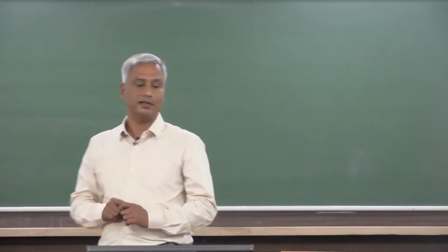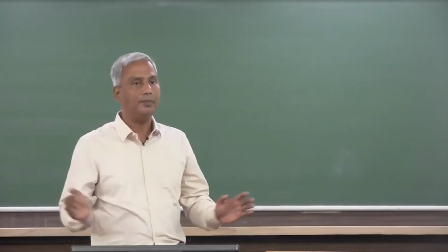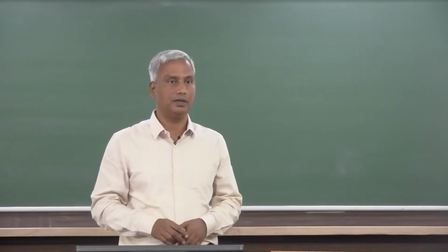So, what will you do in that case? I will also increase the cross sectional area of the conductor. As soon as I increase the cross sectional area of conductor in such a way that my overall resistance comes down, then I will go not even to a milliwatt, maybe microwatt, and then my energy consumption because of the heating of the bus bar will drop. Heating is nothing but waste, you cannot utilize that energy anywhere. Or I will reduce the current. If I am able to do it in both ways, I will be able to reduce my wastage of the energy.